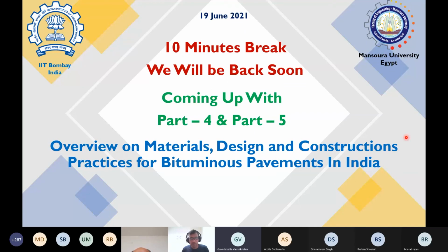Yes, thank you, Vamsi, for such a nice presentation. You have covered a wide spectrum of mix types, right from the dense graded mix to the gap graded, currently practiced in India. We have nicely covered various aspects, such as aggregate gradation and different volumetric requirements for different mix types. You have also given a little glimpse of future plans for shifting from the Marshall mix method to Superpave mix design, which was nicely covered by you.